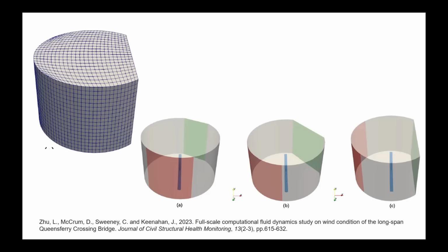So we don't just look at the prevailing wind conditions, we consider north, south, east, and west at a minimum, and perhaps northeast, southwest, and so on. So every time we change the inlet, we need to change our mesh. This becomes extremely tedious when you're dealing with a large mesh.